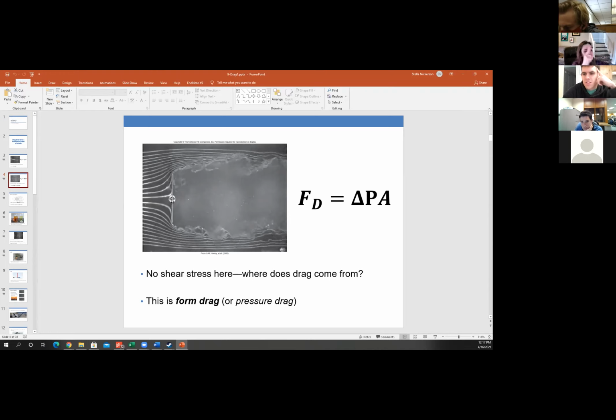It increases because it's your static pressure plus your dynamic pressure. Yes, Zach, it increases. Because when the flow hits the solid object, it stagnates, which means its velocity goes to zero, and the kinetic energy that was in that flow turns into pressure instead. So at the front of this object, the flow hits it, stagnates, the pressure increases. At the back of this object, this turbulent wake has a lower pressure. And so that means that you have a high pressure in front, a low pressure in back, and you will get a net pressure force pushing you back.